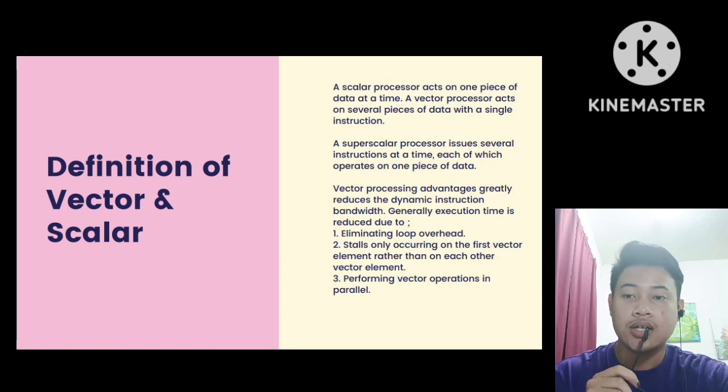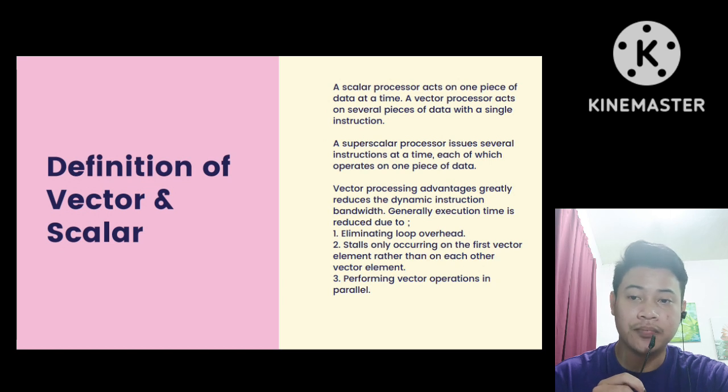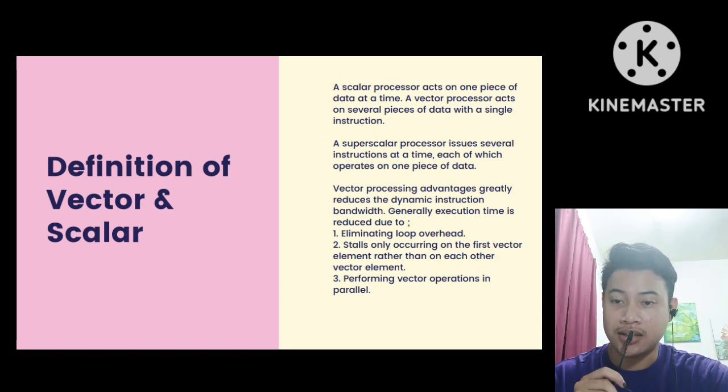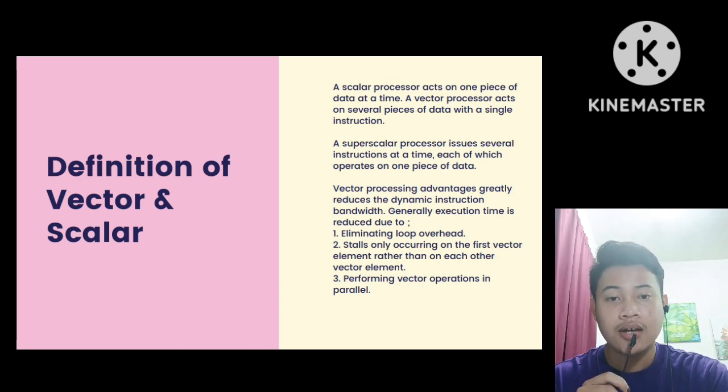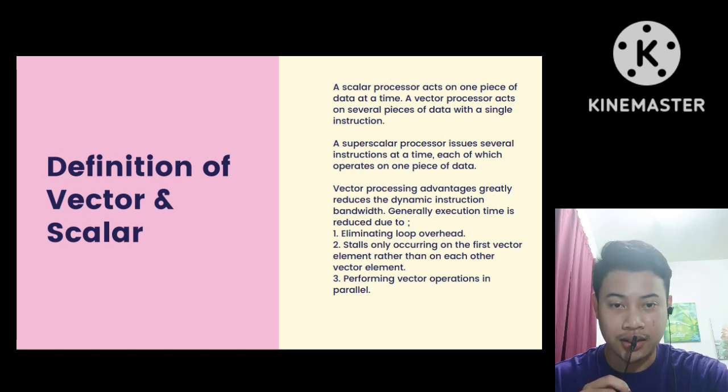Vector processing's advantage is that it greatly reduces the dynamic instruction bandwidth. Generally, execution time is reduced due to eliminating loop overhead, stalls only occurring on the first vector element rather than on each other vector element, and performing vector operations in parallel.